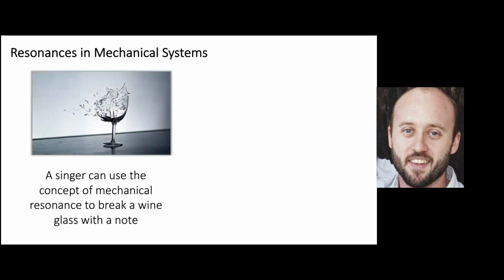And we can think of this conceptually if you think of the classic example of an opera singer singing a specific note and breaking a glass. What is actually occurring is the opera singer has an ear tuned well enough to know what the natural frequency, or one of those natural frequencies, of the system is. And then if the voice is sung at a pitch that matches that natural frequency, we get that concept of resonance, where that voice input is being amplified and it shakes the glass at a greater level and it causes that glass to break.